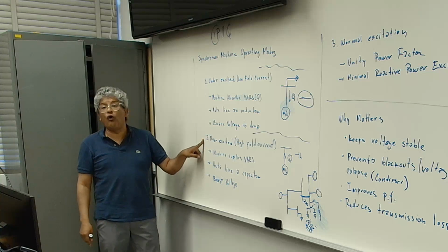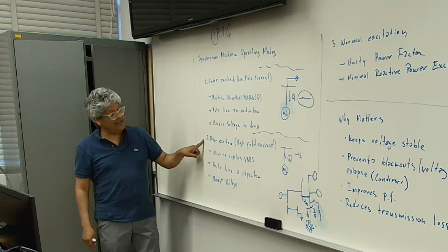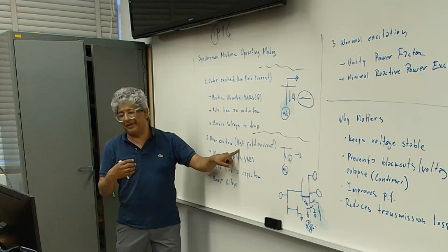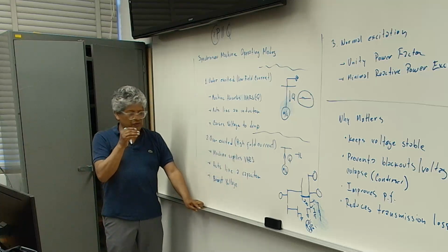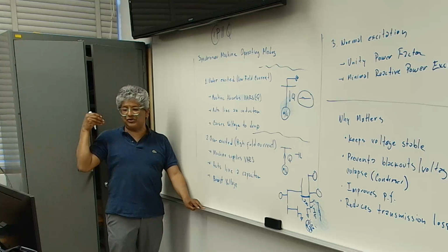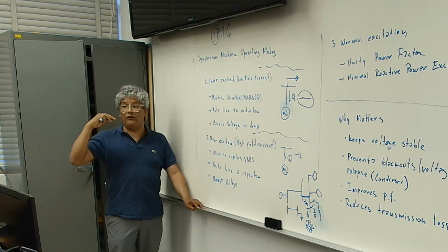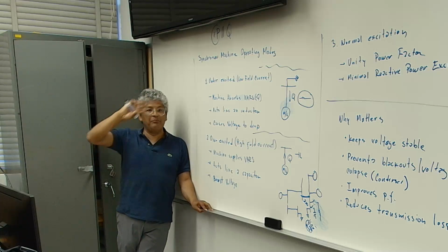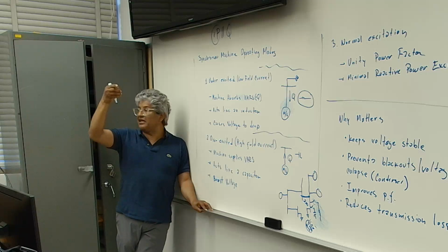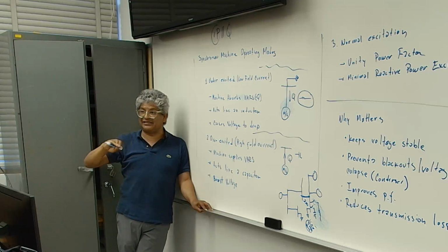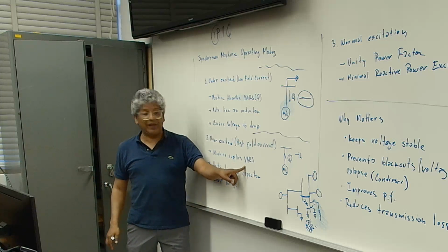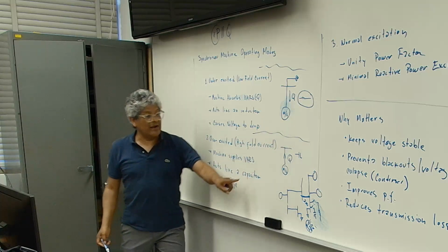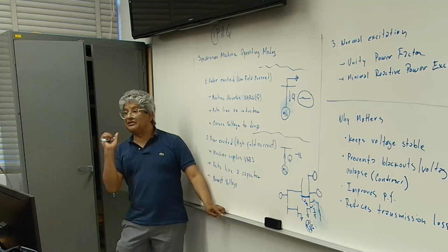The second operating mode is overexcited. When the machine is overexcited, the field current increases, and increases with time. You get to a point where the machine goes from under excitation, and the flow of the vars is higher. You remember when you were recording the Q, it was positive, and boom, went negative, right? So basically, you're taking the machine from under excitation to over excitation. So the machine now supplies power, injecting vars to the system, acts like a capacitor, right? And boosts the voltage up.